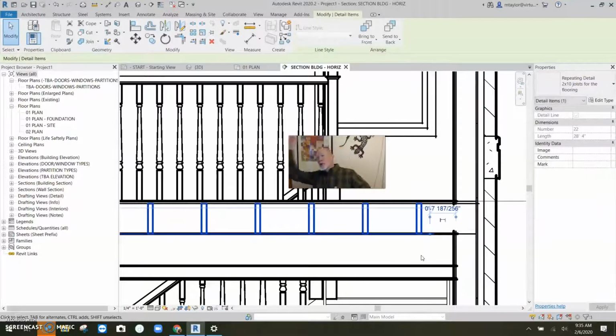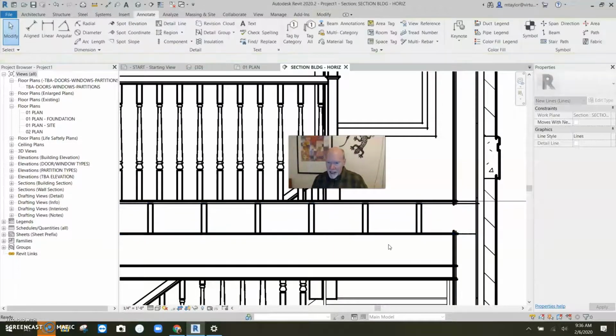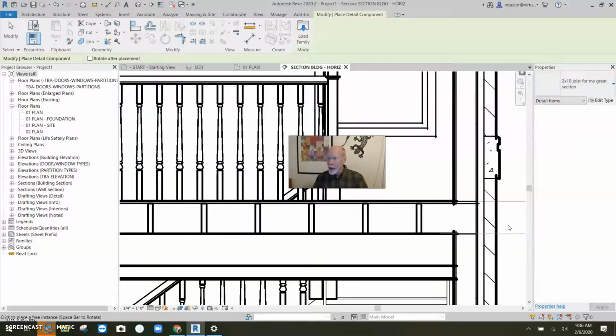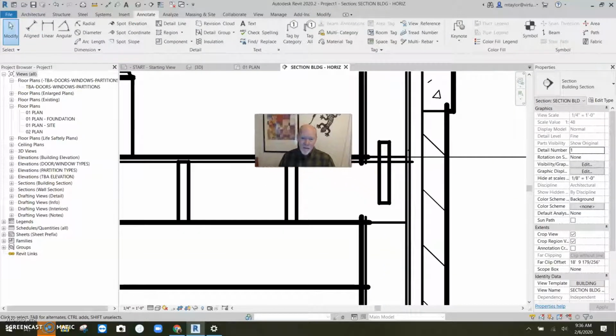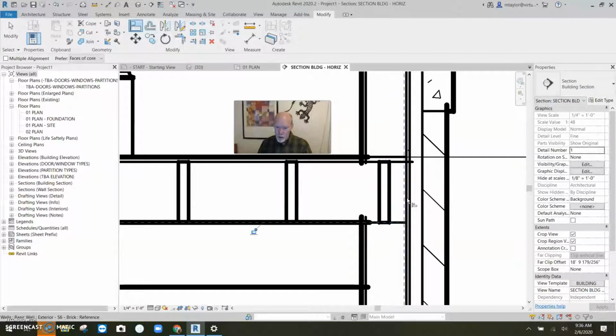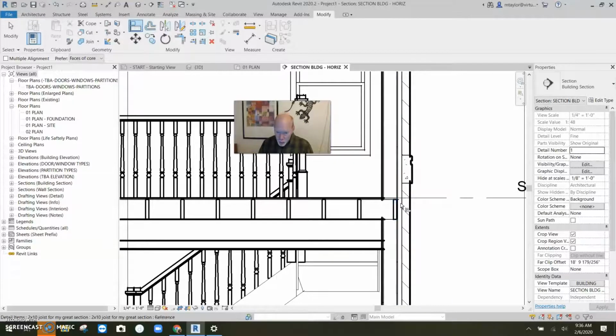If it threw the last one way outside the wall or right close, you can stop short, okay? Pull your cursor, stop short, and then pull a single detail for that. I would just go up to Component and grab my joist, and I can bring one in here. Now, the best thing about these is, hey, get my face out of the way. Okay, there. The one good thing about this is you can go align and lock. You can use align and lock to get these to move where you want. Let's just say you wanted it right there. So if your spacing's not perfect, you can put a single at the end.